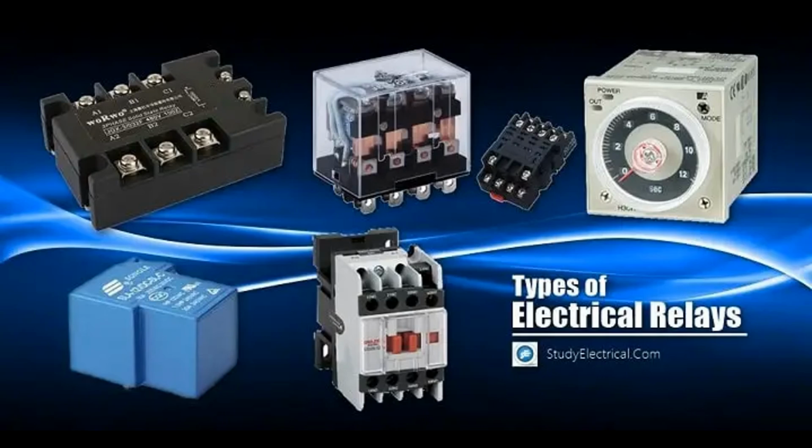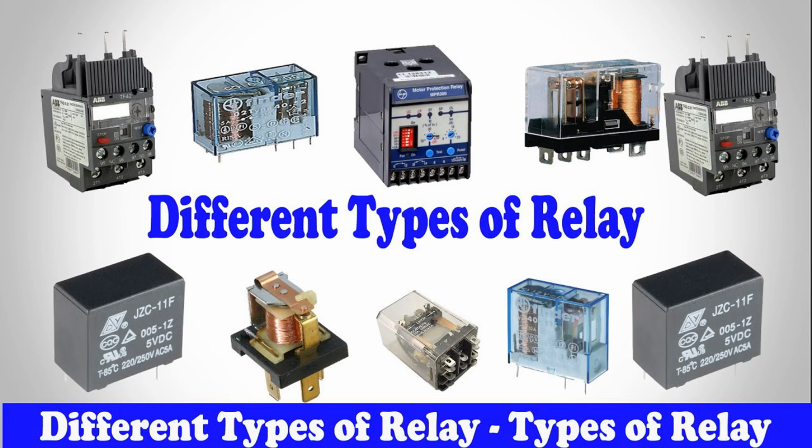The output circuit of a relay is the portion of the relay where the controlled electrical contacts are located. It's where the relay's switching action connects or disconnects the load or device being controlled. The output circuit typically consists of stationary contacts, movable contacts, and terminals for connecting external circuits or loads. Here's how the output circuit functions in a relay. Stationary contacts. These are fixed contacts within the relay that provide the terminals for electrical connections. They remain stationary and do not move during the relay's operation.